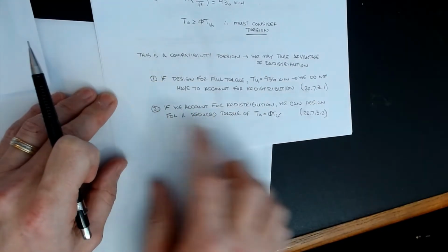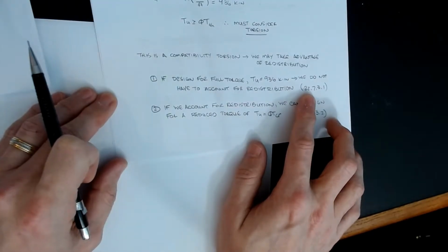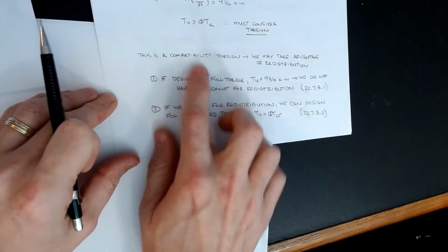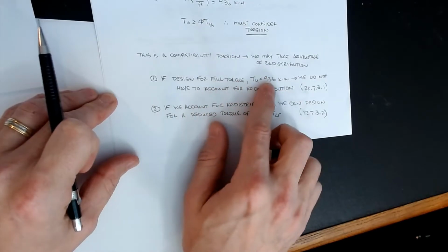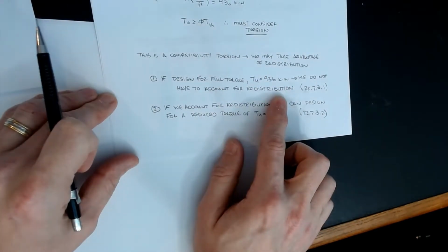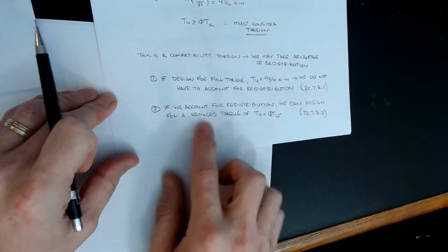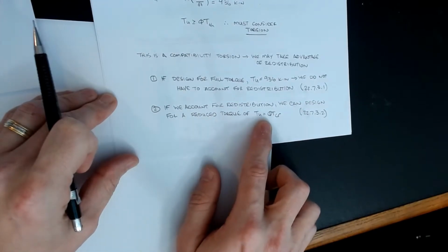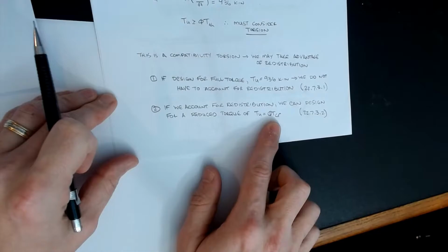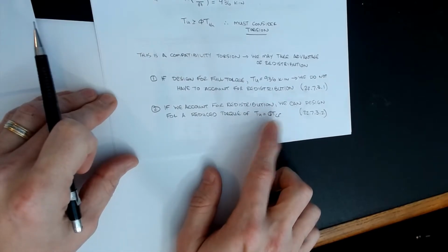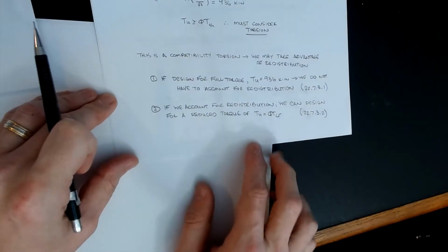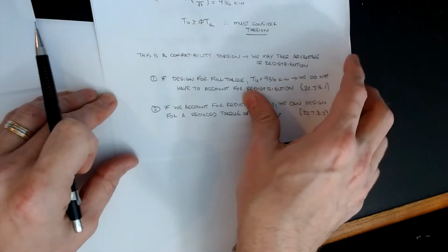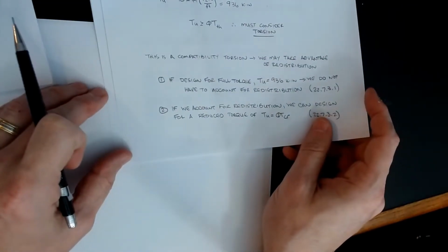But let's go through the procedure. There are two requirements, and they're located in 22.7.3.1. The first one says if it's equilibrium torsion, my option when it's compatibility is I can design for the full torque value of 936 and I don't have to worry about redistribution. Again, that's 22.7.3.1. But if I want to take advantage of redistribution, I can design for a reduced torque of T_u equal to the cracking torque. Well, what's the cracking torque? It's 4 times the threshold value. So I can either design for 936 or I can calculate the cracking torque value, and that's what we're going to do next, just to show the number that you get. Everybody good so far?